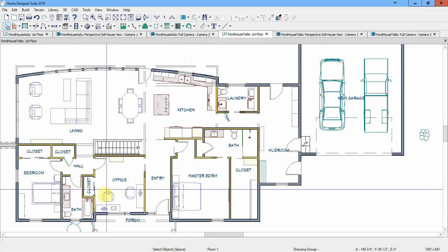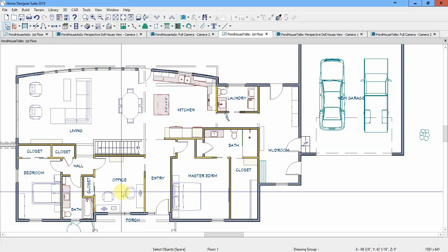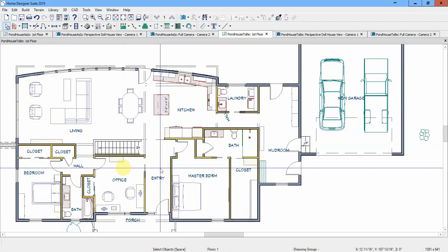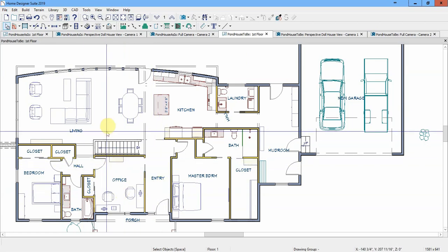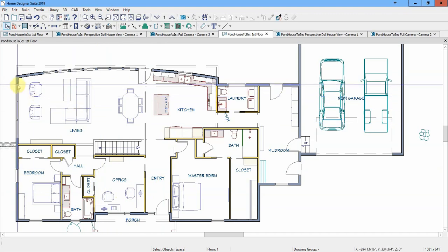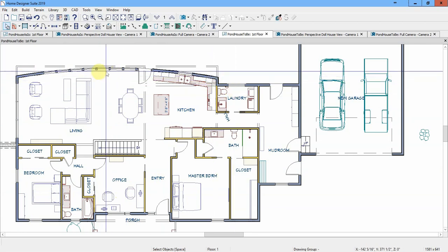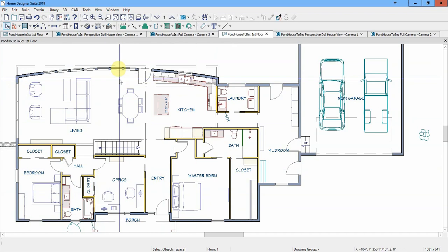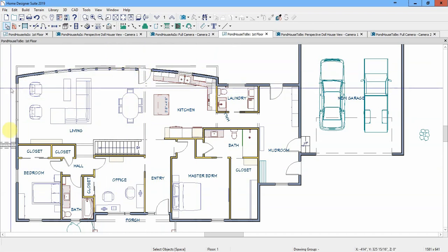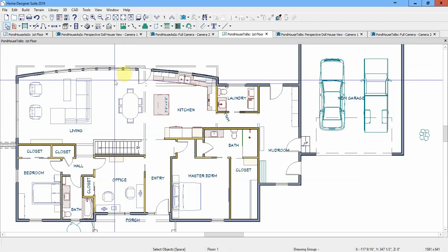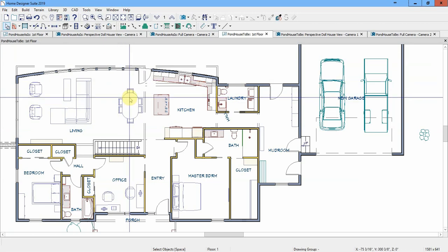We took this 1 bedroom in the front here, and we converted it to an office with pass-through doors. And then another thing, probably the biggest change in the whole house, is that we took this old wall and removed it completely, pushed it out 2 feet on each side and 4 feet in the middle to create this bowed wall, with 7 windows, a glass door, and 3 windows on this side with awnings that open up. So that really opens things up. And if you've seen the videos, you've seen the light that comes in through this room.